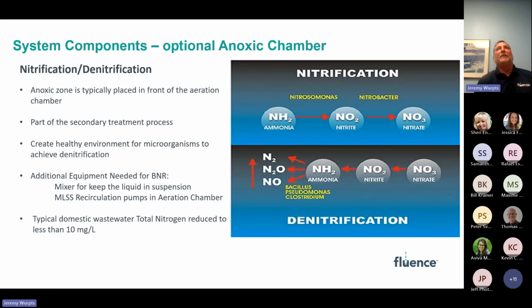And then again, we do provide, in some applications, an optional anoxic chamber for nitrification, denitrification. And that's typically placed in front of the aeration chamber, and it's part of the secondary treatment process.